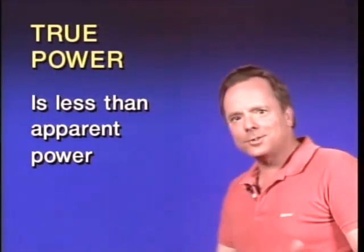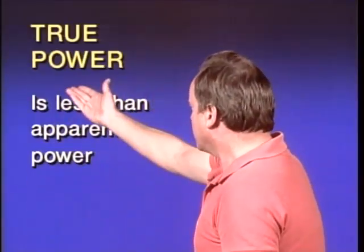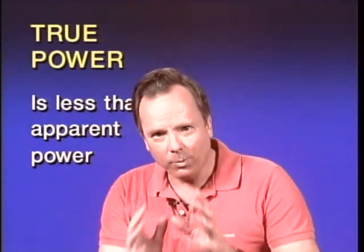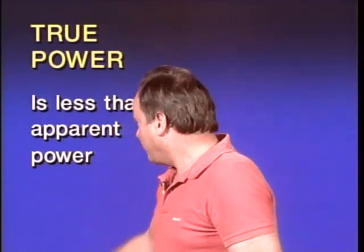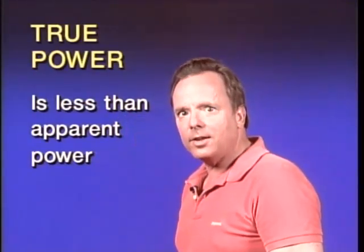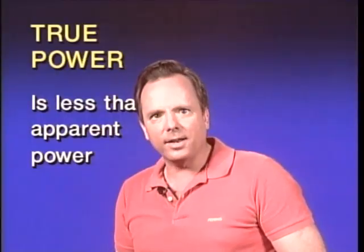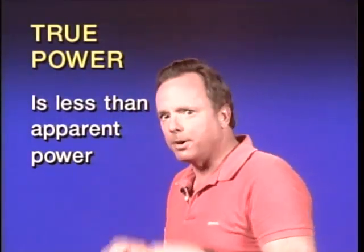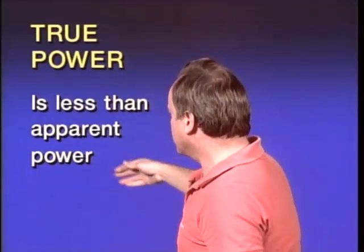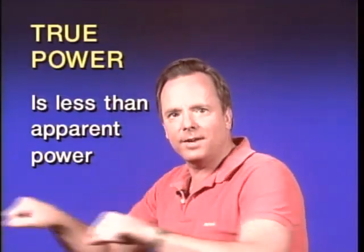Now here is the answer to the last question we need to cover about AC circuits, and the answer is true power is less than apparent power. Let's talk about what we mean when we say that. Well, if you have inductive reactance or capacitive reactance in an AC circuit, they tend to throw the current out of phase. And that's kind of like having three guys trying to get a car stuck in a mud puddle out of that mud puddle by rocking the car back and forth. Well, if you have capacitive reactance or inductive reactance in the circuit, it's like two of those guys rocking at different times than everybody else.